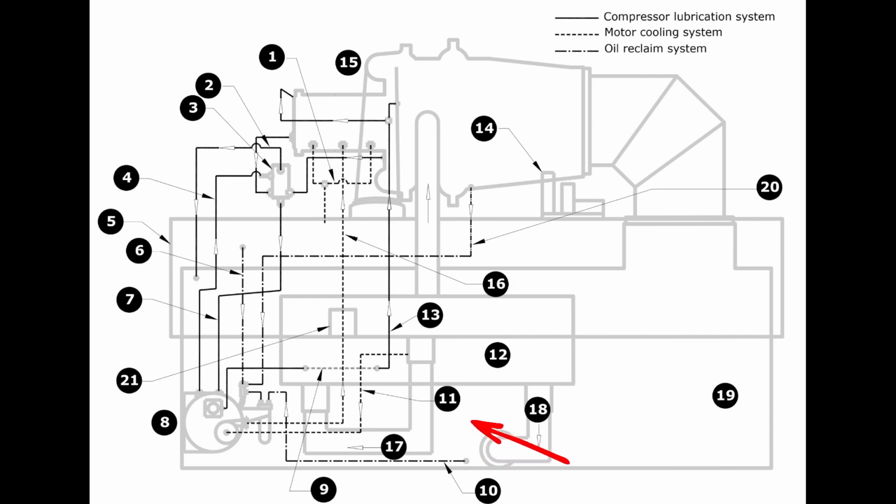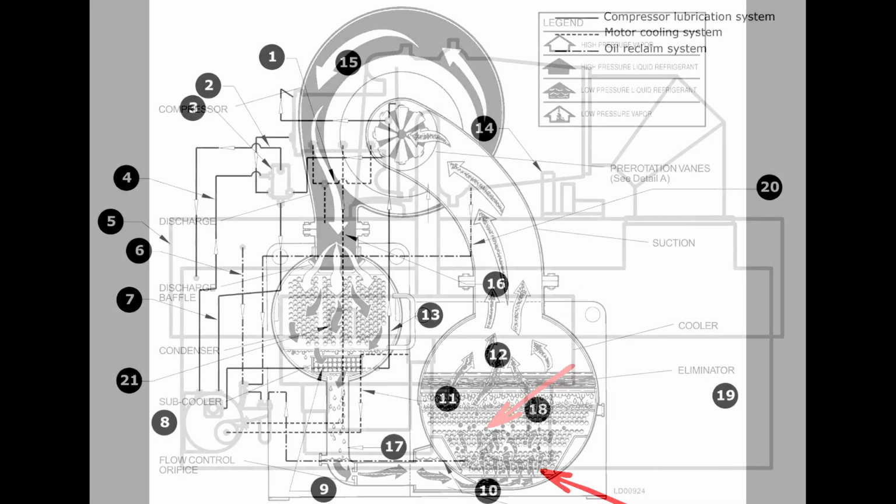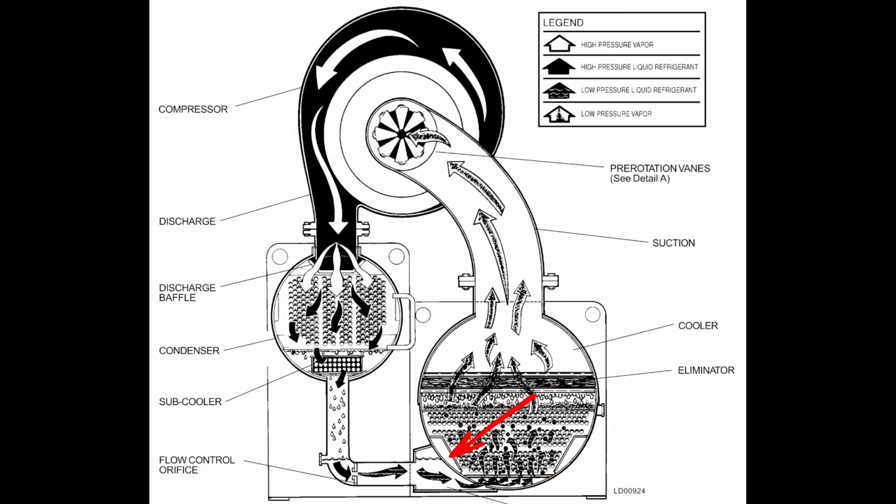These CVHs are flooded machines, so the liquid refrigerant gets inputted into the bottom of the evaporator instead of coming into the top. And there's a distribution rail in the bottom of the evap. We can see that here in this example. There's this rail assembly here at the bottom, and that distributes this. This comes into a single point and then hits this rail and it gets distributed across the length of the evaporator.